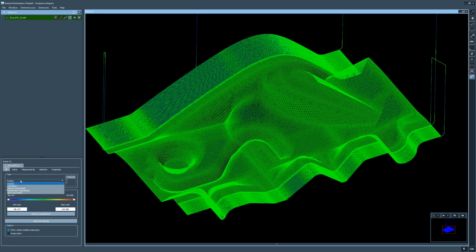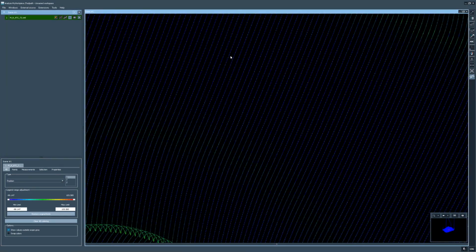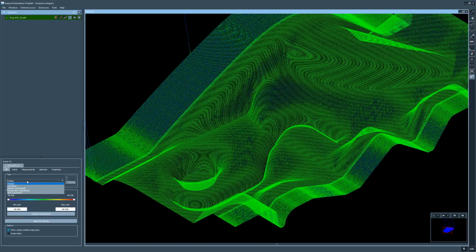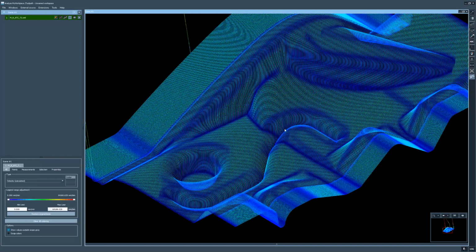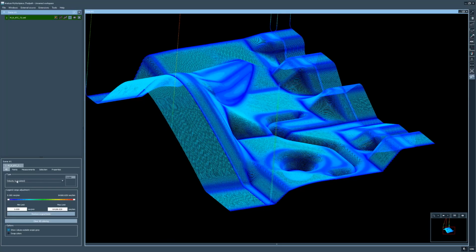Basically, what you can do with it is visualize scalar data on your point cloud. Whenever there is scalar data available, so basically just data points that are mapped to the points in the point cloud, you can visualize them. So let's start with a typical example. Let's visualize the velocity of the tool center point alongside the tool path. First of all, if you click on it, that's the calculated velocity, so the velocity that Toolpath automatically calculated.